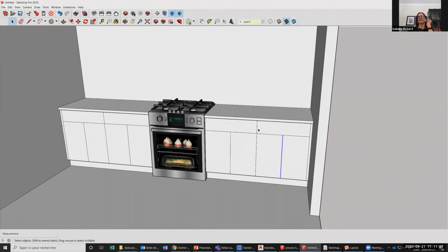If you are really into details, make sure you click one segment and then click the second, holding shift, if you want them to move all together. If not, there's only one that will move, but see, the end point of the segment that is not selected will move as well, but it will not keep a straight line. The line will now be oblique, right?